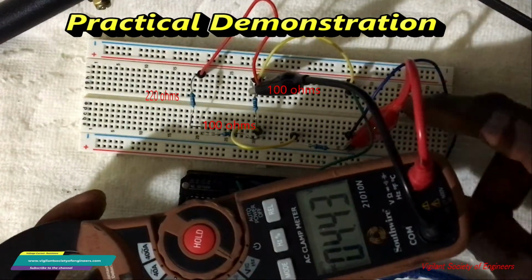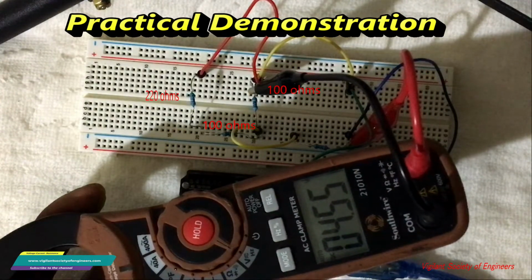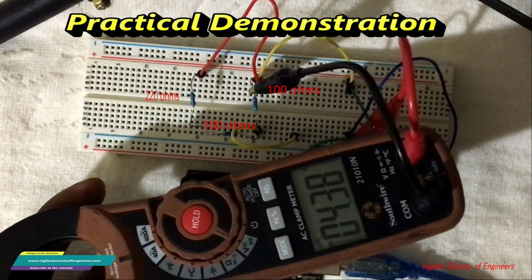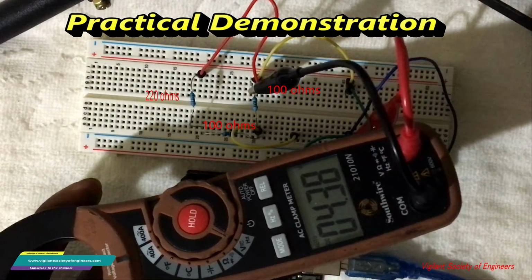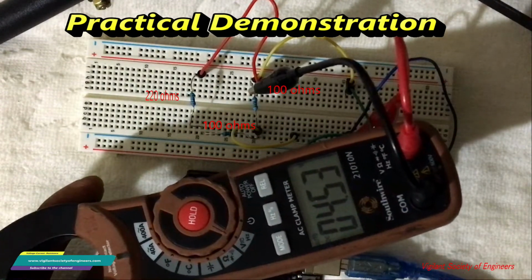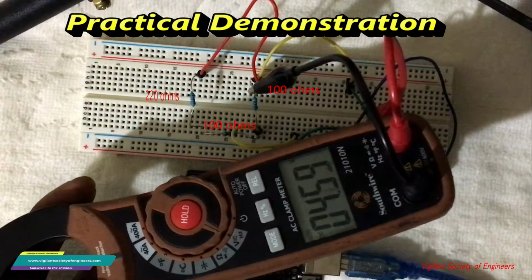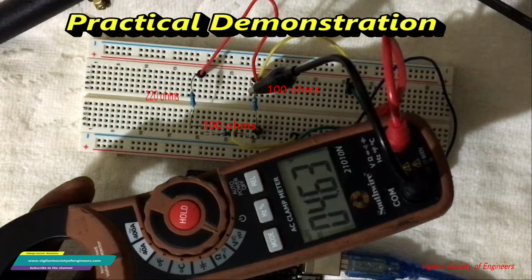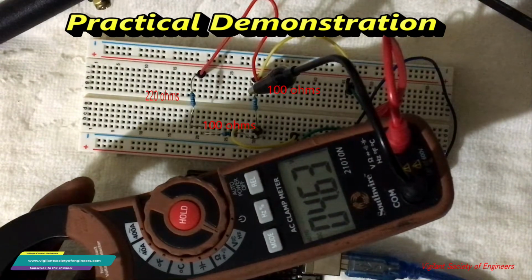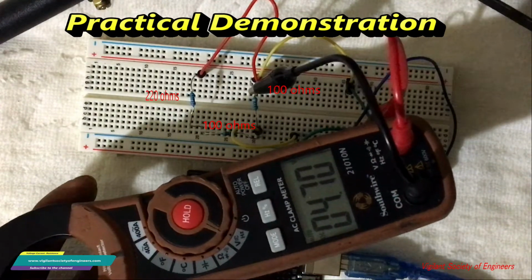All right, so this is what happens when it comes to this kind of circuit. There's a lot of losses within the supply. Sometimes we may have poor contact across the jumpers and the resistors and so forth. So my voltage is fluctuating between 4.0 and 4.616362. All right, so the voltage basically is fluctuating.